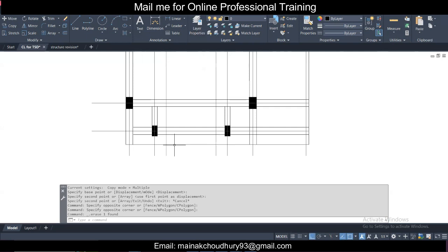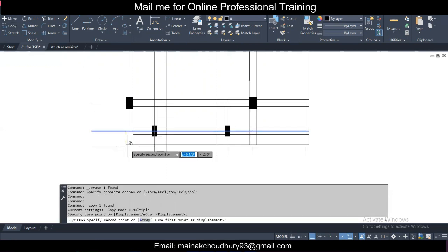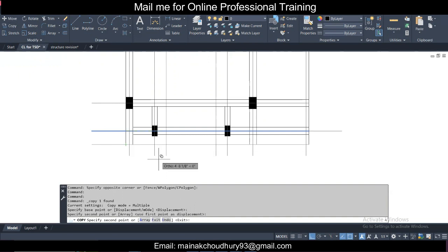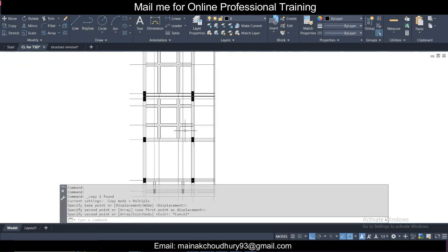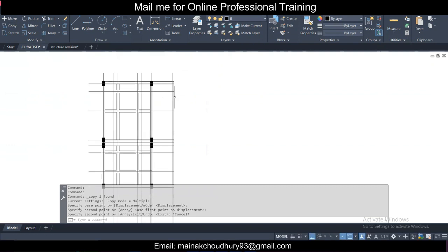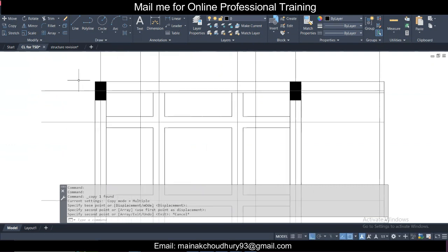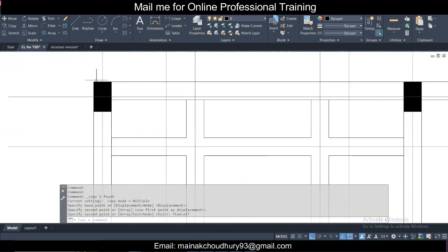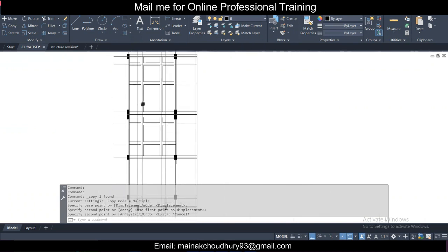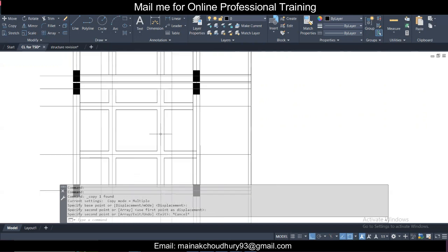And similarly, this portion is too close. I don't need to give a beam here because it is too close and there is no significant load. So I'll just place this up to here. This beam can go up to there. Okay, so this is the case, and we have pretty much covered all the centerline aspects, I believe so. Okay, yeah, so I think this is done.